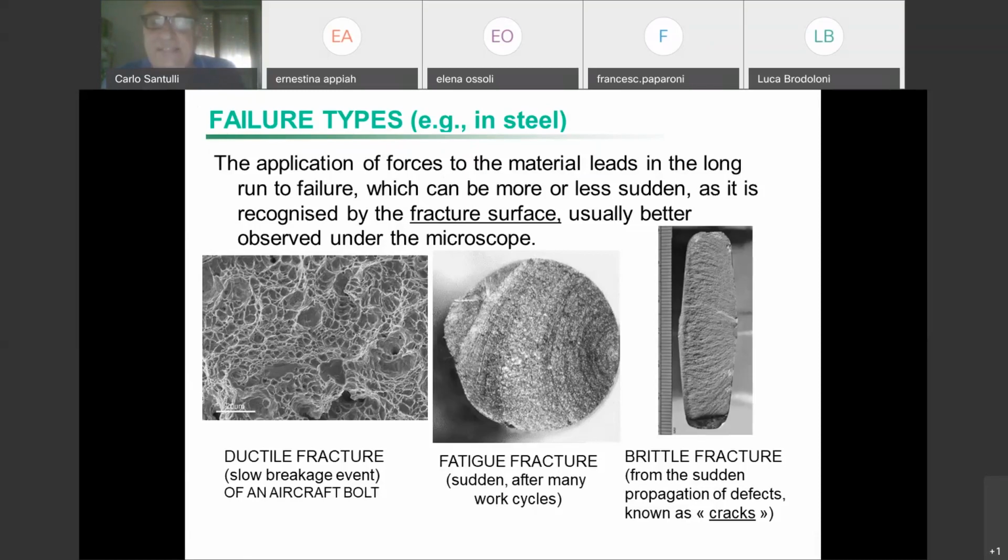And even if there were no visible cracks, they were able to explode because fatigue was producing this kind of vibration, which you can see, and these rings. Fatigue is recognizable by these rings, which give you the idea of very fast propagation of the crack, but at very low load. So it's not comparable with proper rooted fracture. We'll talk about that later on anyway.